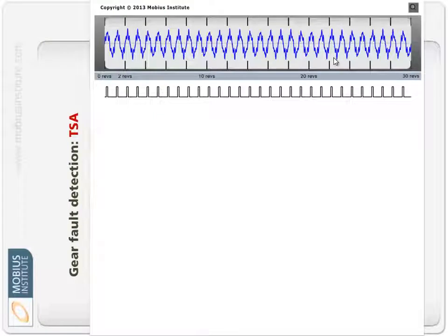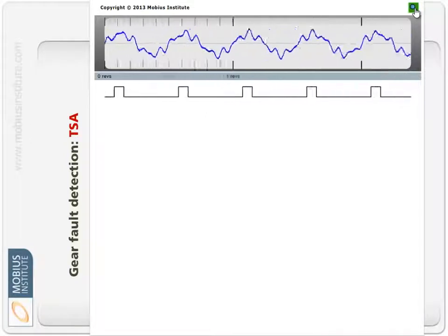Now, let's consider another way of collecting our data. In a normal analyzer setting, when you walk out to the machine, even if your analyzer is set up correctly, and you press the start measurement button, it will just start collecting the data, just sort of like I described before. So here's the vibration, whatever it is, and these little marks indicate revolutions of the shaft, and down here I've got my tach signal just for now as a reference. So let's just zoom in on that.